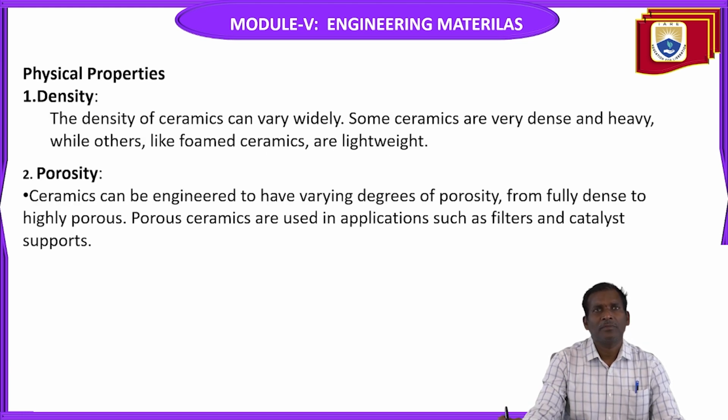Physical properties, density. The density of ceramics can vary widely. Some ceramics are very dense and heavy, while others like foamed ceramics are lightweight. Porosity. Ceramics can be engineered to have varying degrees of porosity. The porous ceramics are used in applications such as filters and catalyst supports.